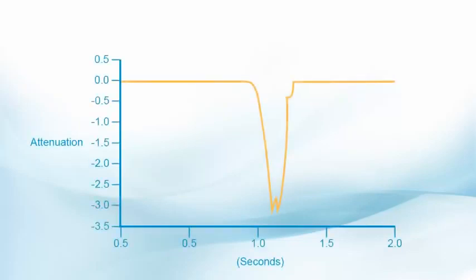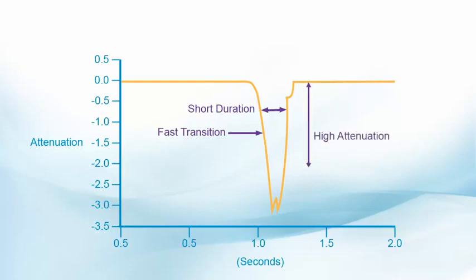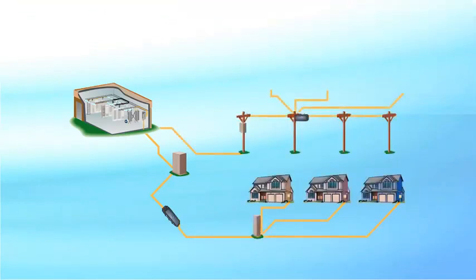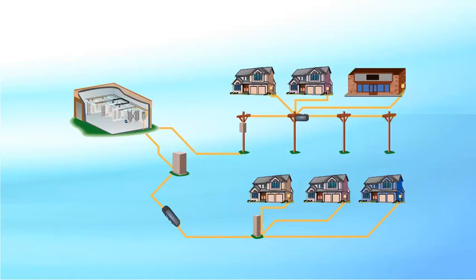The figure shows a typical transient loss recorded when an installer handles fibers. These are fast changes in attenuation up to 10 dB, with a duration from 1 millisecond to several seconds. The transient loss should be reduced to a level below 0.5 dB to avoid transmission errors or bit errors in an active optical circuit. In network locations that require frequent intervention, such as the access or optical distribution network ODN, it makes sense to separate the optical fiber circuits by storing the fibers on individual splice trays. This reduces the occurrence of transient optical losses in adjacent circuits.